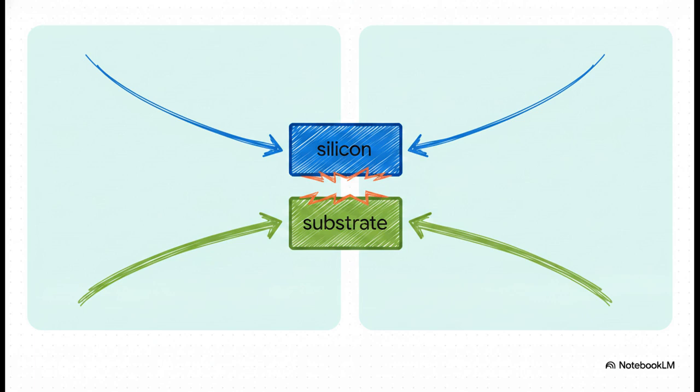We've got the rigid silicon die, which expands at a pretty slow rate of roughly 2.6 parts per million per degree Celsius. But it's attached to an organic substrate that expands at 15 to 17 parts per million. Think of it like building a road out of two completely different materials glued together. That massive expansion mismatch creates severe, relentless structural stress that literally tries to tear the chip apart.